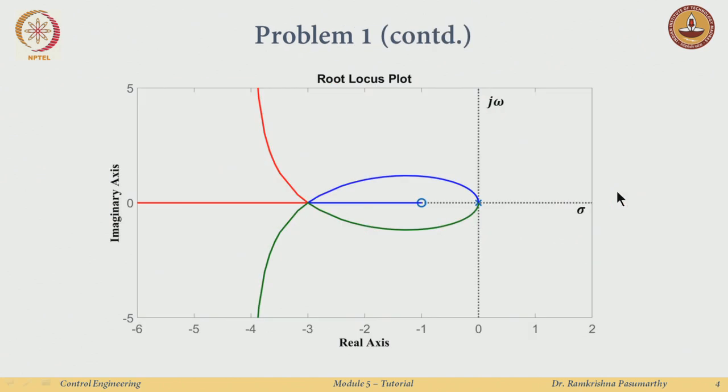Okay. So, all the steps are clear, right. So, this is how it goes. I just do not draw further to the left because there is nothing happening there. So, there are 2 roots here, they meet at minus 3, which is the break in and break away point. So, roots break in here and they also go away from here, and then there are 3 guys which come in, 1, 2, 3, and then they go away here, here and here. One pole is going to the 0 here, the remaining 2 poles are going to infinity. So, that is just following all the steps as before.